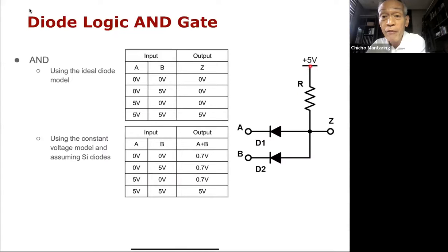So this is going to be an open circuit. And then you have 5 volts here, 5 volts here at this point. I'm talking about this combination. Then also the open circuit voltage across this is going to be 0. So this is going to be an open circuit. And therefore, if both these diodes are open circuit, then what is the value of V sub Z? That's just equal to 5 volts, assuming that this is not drawing any current. So that's going to be equal to 5 volts.